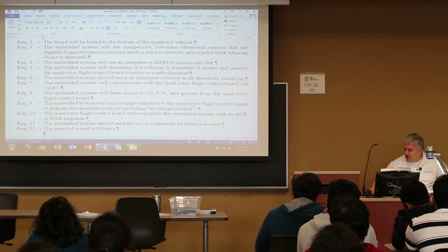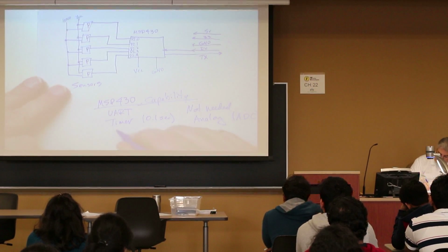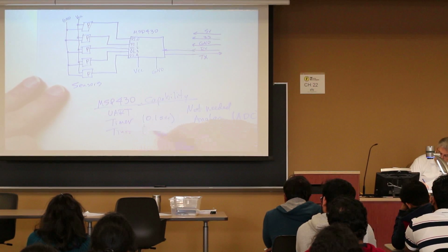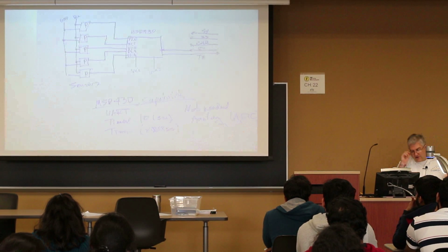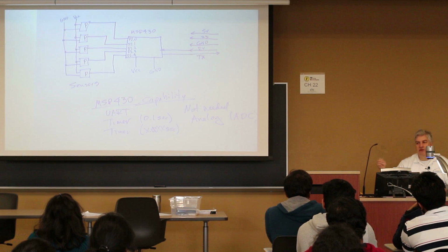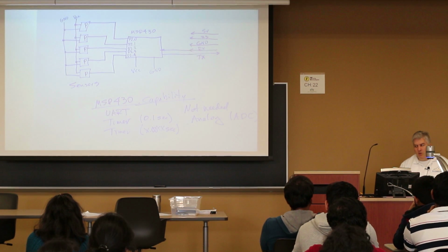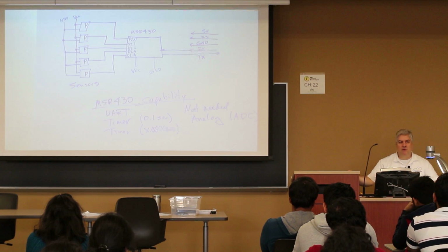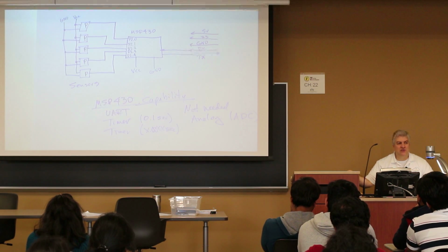So now we know in our system here, we're going to have another timer, and it's going to run for a certain amount of seconds that will help us identify when something didn't come back. Now, here's a question. How well do you know how ultrasound works? It works at a high frequency, right? Typically somewhere between 30 and 40 kilohertz. You can't hear it. Can you ping all 5 sensors at the same time?